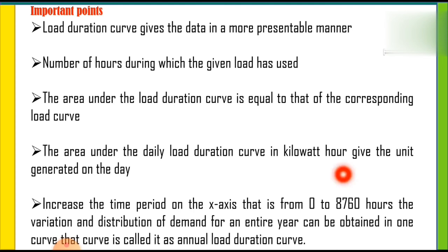We can increase the time period on the x-axis, that is from 0 to 8760 hours. The variation and distribution of demand for an entire year can be obtained in one curve, so that curve is called the annual load duration curve.